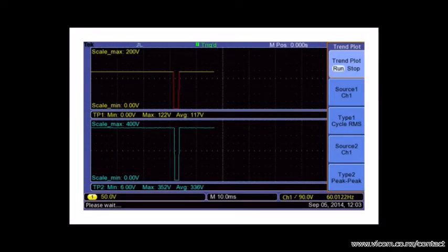The plot displays a red highlight if the measurement data is questionable, for example, if the signal is outside of the display range or if the measurement cannot be calculated. This example shows how a cycle RMS measurement is suspended when line voltage drops to zero temporarily.